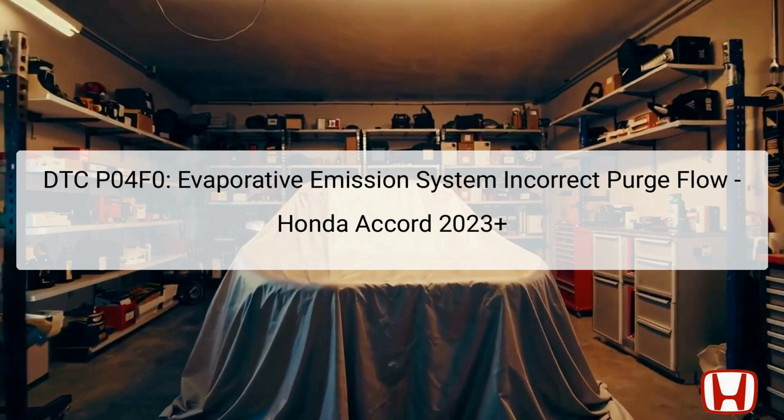The DTC P04F0 indicates an issue with the evaporative emission (EVAP) system's purge flow. This diagnostic trouble code is activated when the powertrain control module (PCM) detects that all components related to the EVAP canister purge valve function normally, yet there is an abnormality within the EVAP system itself. The EVAP system is crucial as it captures fuel vapors from the fuel tank and routes them through the engine for combustion, preventing harmful emissions from being released into the atmosphere.